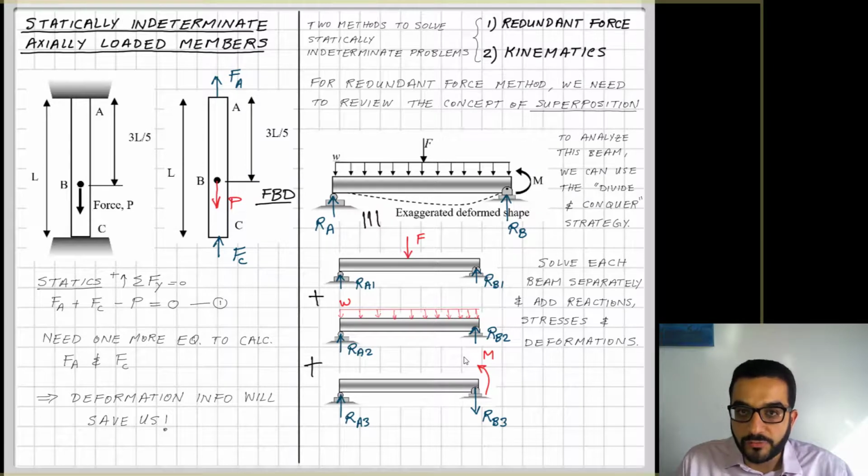And you don't have to do a lot of calculations to figure out the original beam that has multiple loads in it. I can add the impact of each force on the beam to end up with the original case. This impact can be finding the reaction at one support, or finding the stress at one point.